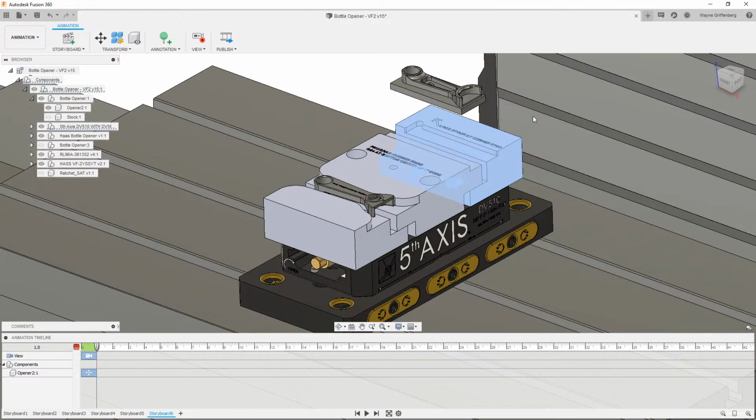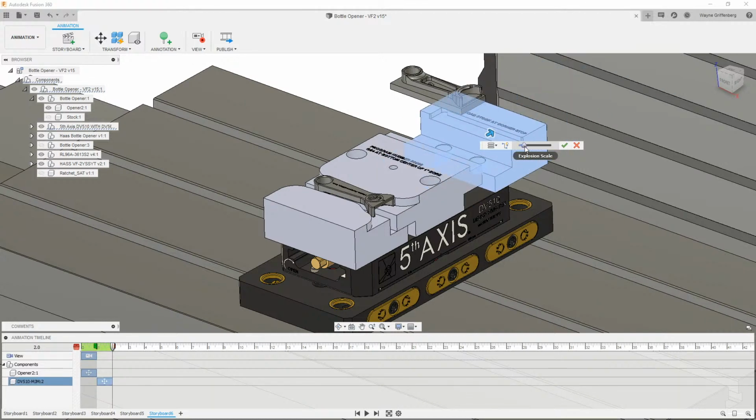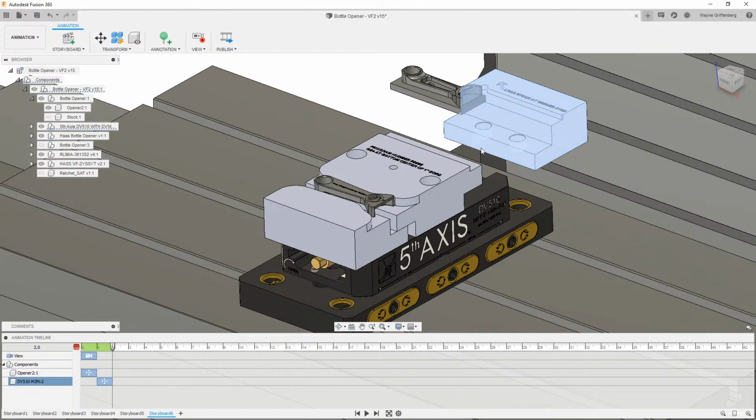This can transform out along any of those axes, and you can do the exploded views directly within Fusion, right? So let's say this one's going to transition in here, and maybe I'm going to transition that jaw out and just walk through that exploded view. If you want to add your extension arrows and lines, it'll do that as well. And you can manually explode your assemblies out, right?